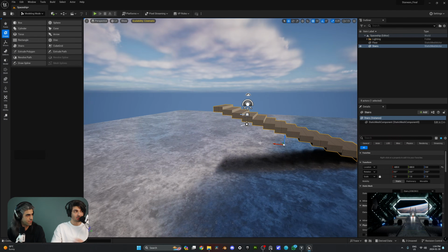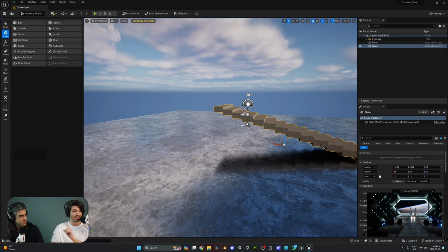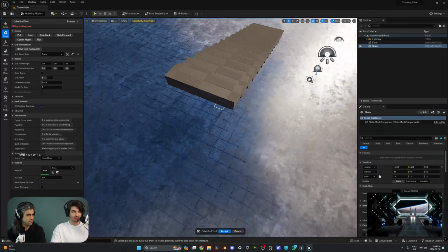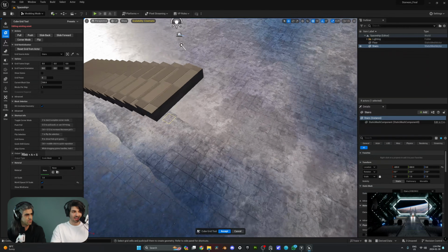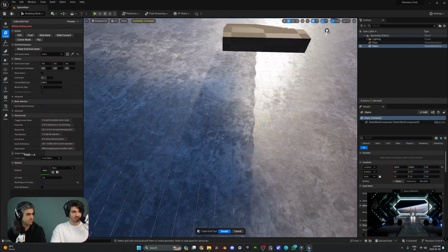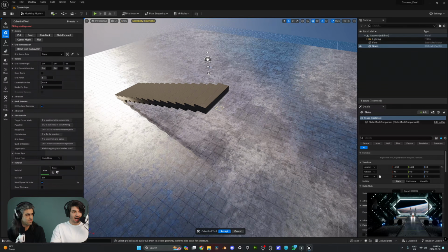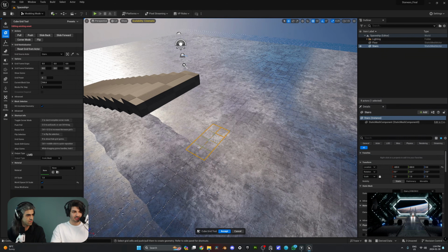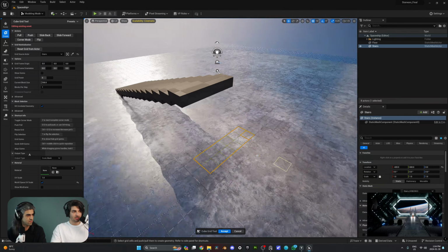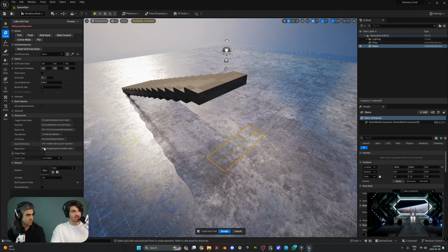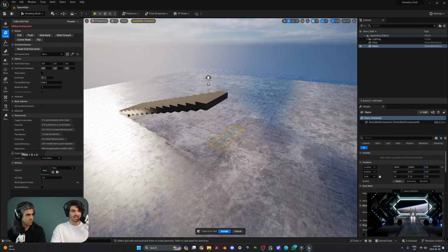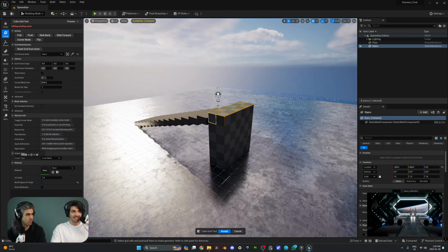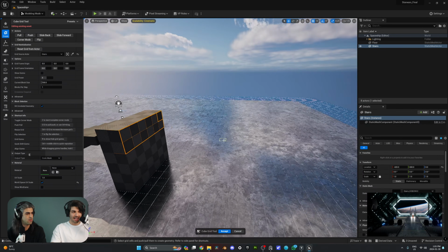And Farhad, I want to show you something really cool. Are you ready? Yes. Okay, this one is my favorite. This one is called Cube Grid. And if you're a gamer, this is going to be very familiar for you. Like, I believe Minecraft or Roblox or some games like that might have similar functions. I now have spawned a grid on the floor, and I can go ahead and click drag to select an area. And then using these shortcuts on the left side, if I go ahead and push and pull, so E and Q, I can go ahead and quickly build a platform.